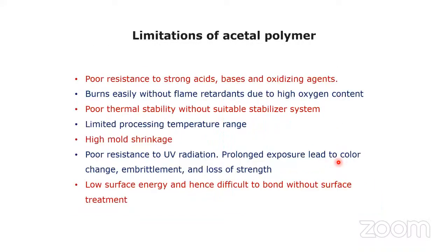As all of the polymers have some limitations, here are the limitations of acetal polymer as well. It has poor resistance to acids, bases, and oxidizing agents. As mentioned in the property slide, it will get oxidized in the presence of some acids and bases. It shows some chemical stability, or solvent stability, but in the case of acids, bases, and oxidizing agents, it will deteriorate.